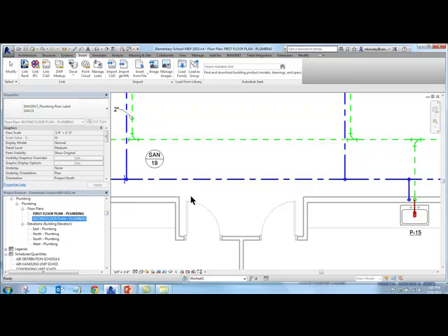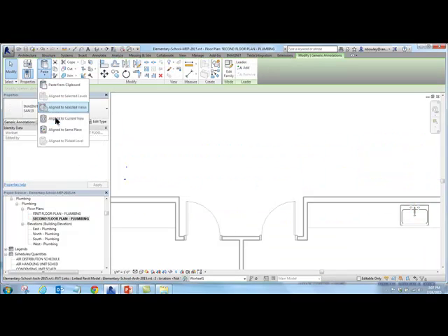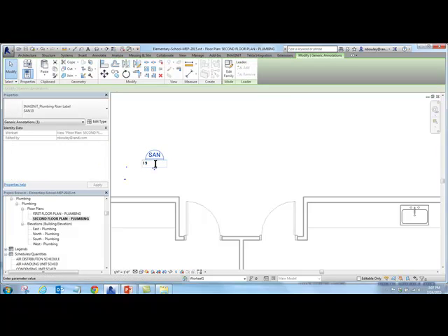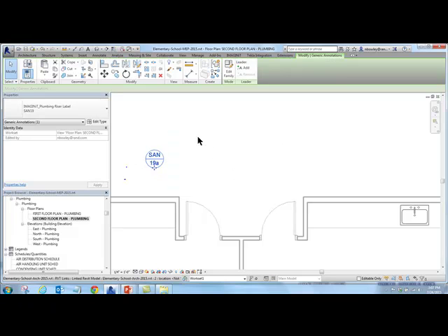Second floor. And we'll do paste the same place. So if somebody came back and said, oh, that's riser 19A, just put an A next to it, and it fixes on all the floors, basically. Also, if you're able to get ISO risers in Revit, you can use those same labels, and if they change in one place, they change everywhere.